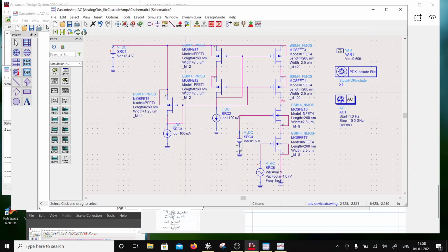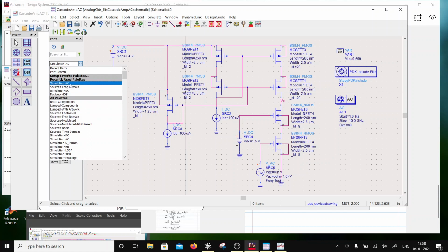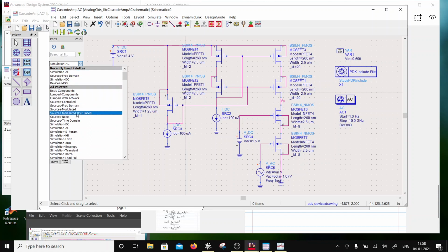So what I would do is I have two options. One is over here, but this is not a gain stage, right? Because this is seeing a load of 2 over gm, right? So I would put here an RC. That would be a form of compensation. I may not be right, but my instinct says that an RC over here would do that.